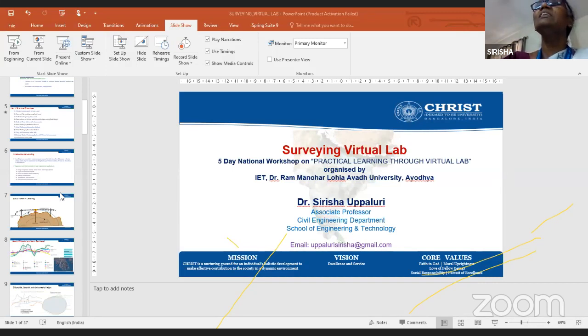If I am establishing geodetic control points, then it is not a transferring of benchmark. We are going to establish a new benchmark for a primary or secondary triangulation network. The Z dimension leveling points, these vertical control points, I am going to establish as new points if I am dealing with first order or second order. If I am at third order, even if I am using less precise methods, nothing will happen to your transferring of benchmark.